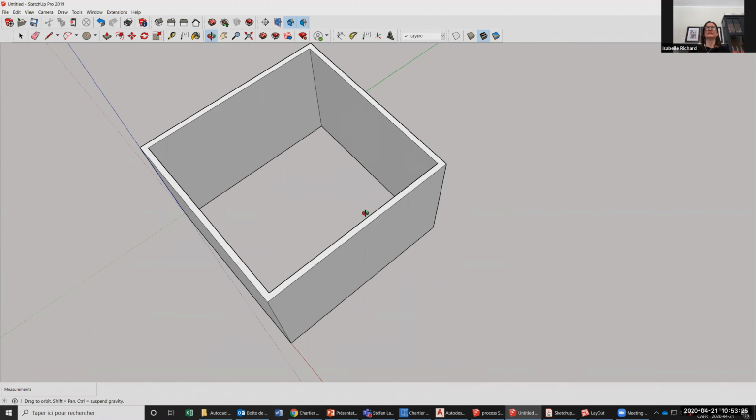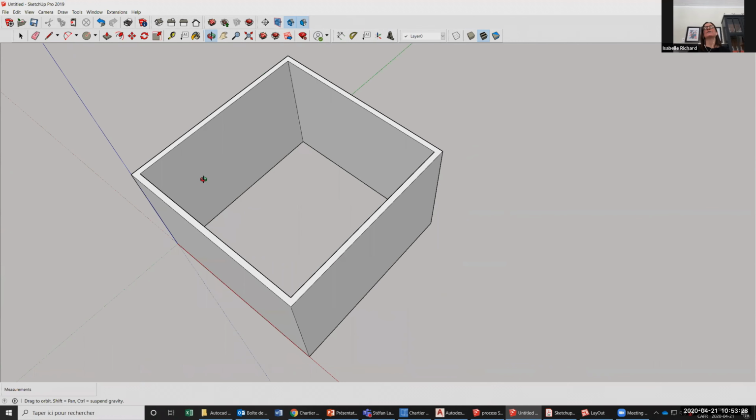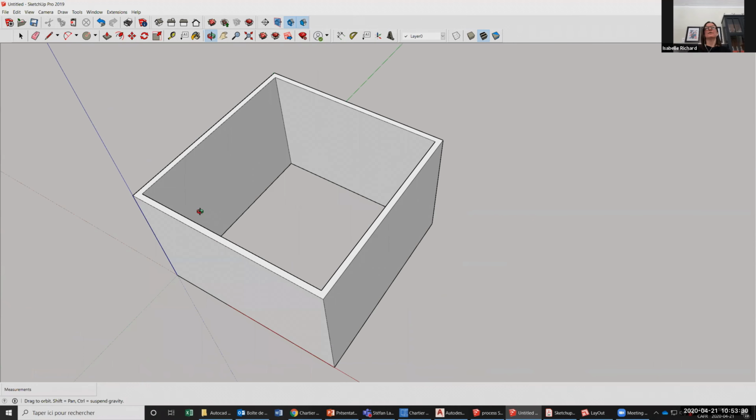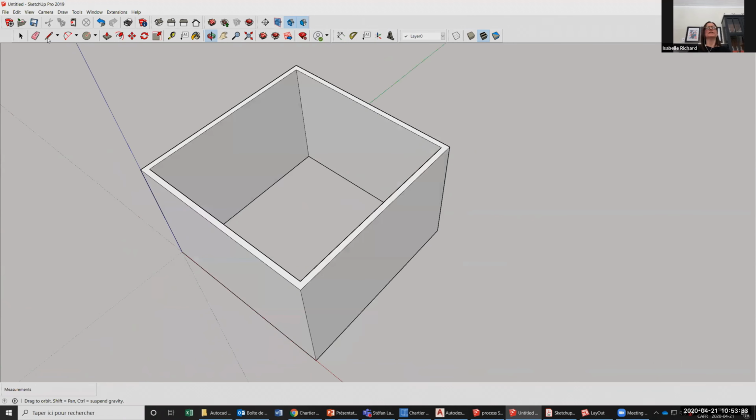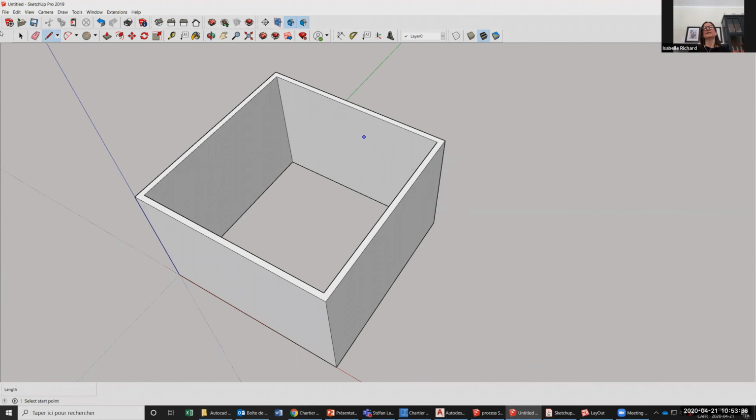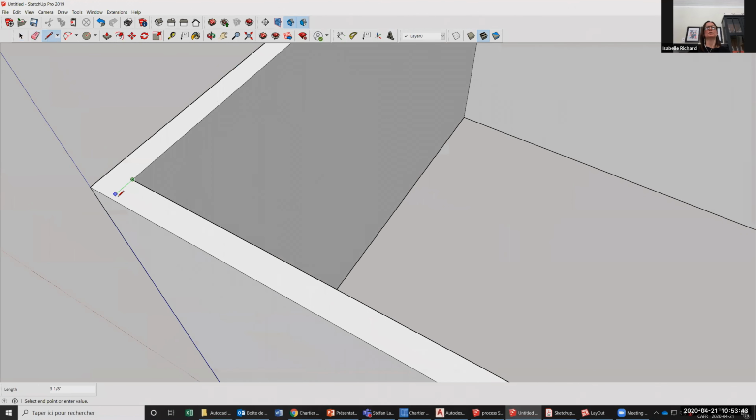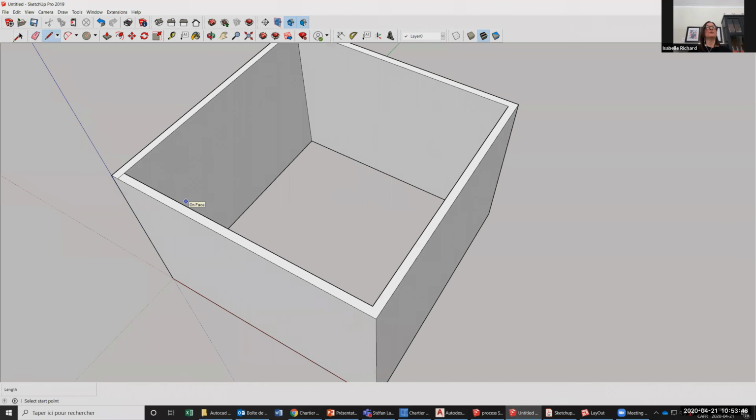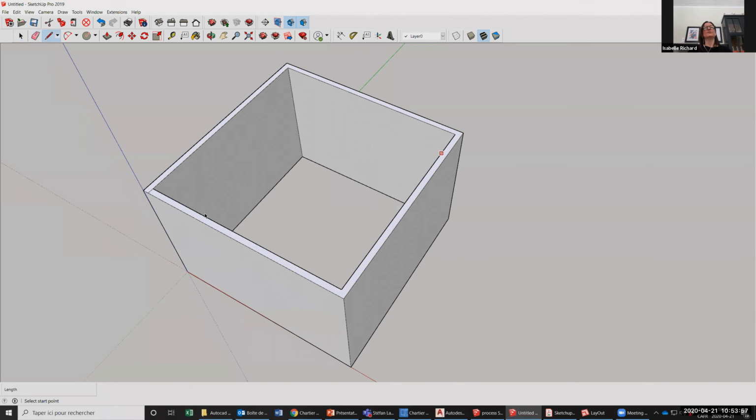I can also change the dimension. Let's say, for example, I just want to have 3 walls, but one part is open. Let's say this part here is completely open. So what I'll do is redraw over my face, create a new segment. This way, by closing down another part of my drawing here, I will create different faces that I can extrude independently.